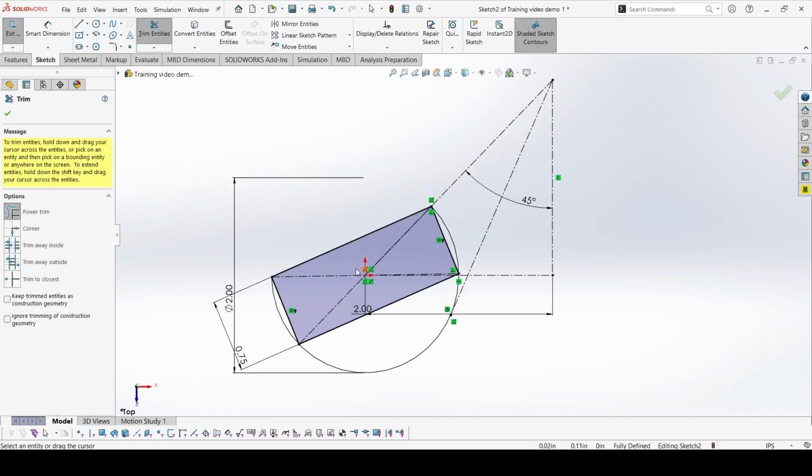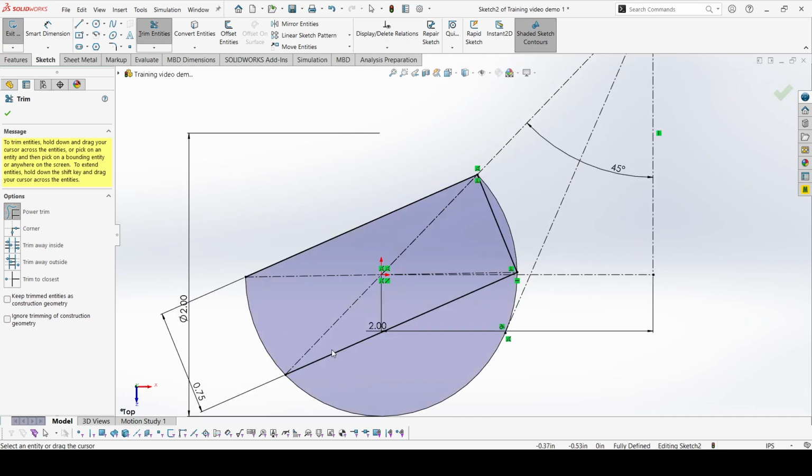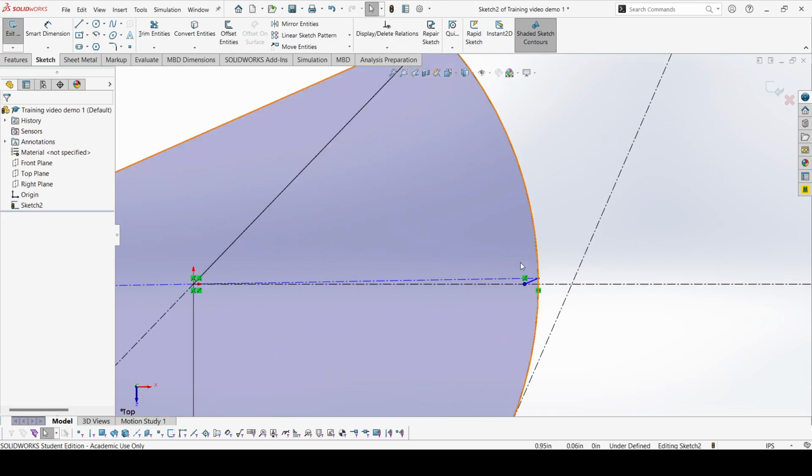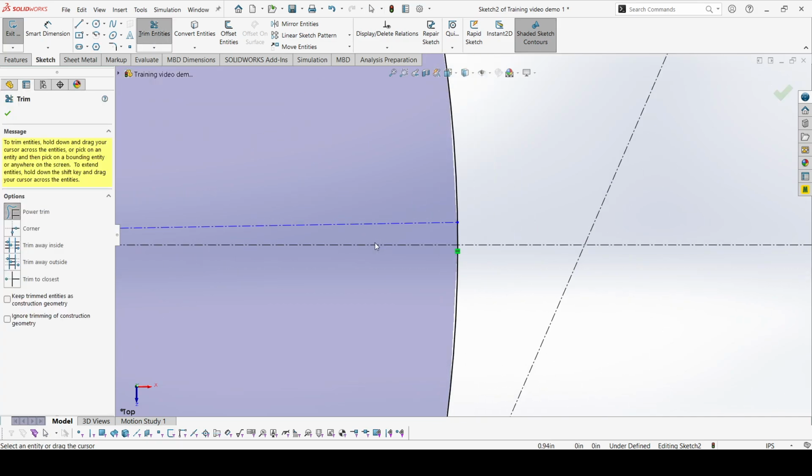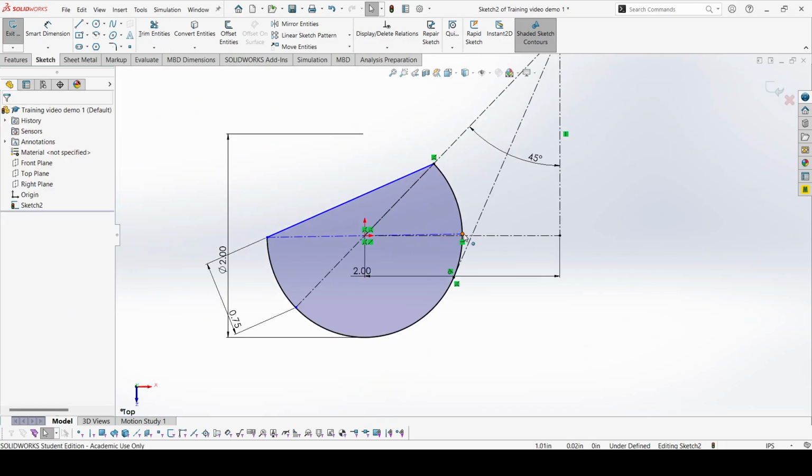That dimension will still work. Sometimes it won't, but it's continuing to work at the moment. Now, you'll notice these lines turn blue as I deleted parts of the rectangle. That is normal, because there's no longer anything defining them.